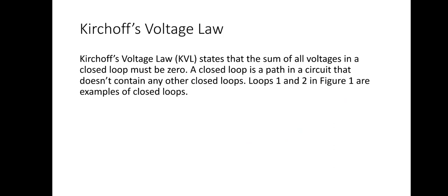Sum of currents entering or leaving a closed surface is zero. Circuit branches can be inside this surface. The surface can enclose more than one node. This could be a big chunk of circuit. Example, black box. Generalized KCL examples. Now, using Kirchhoff's voltage law, KVL.